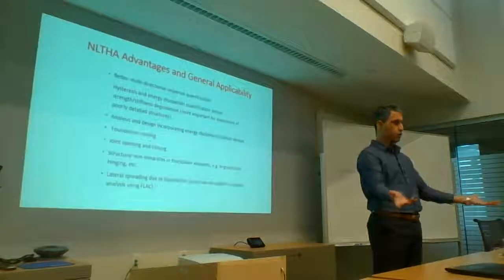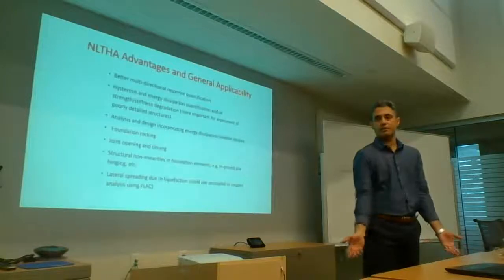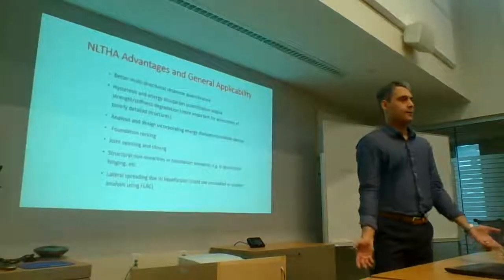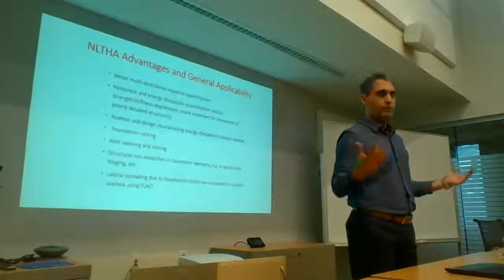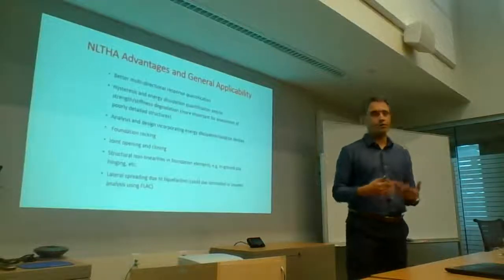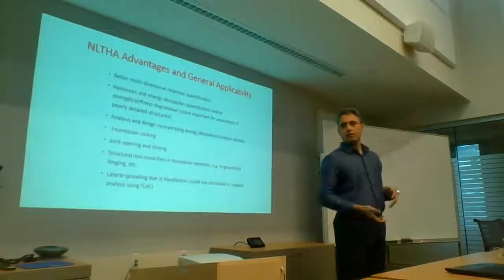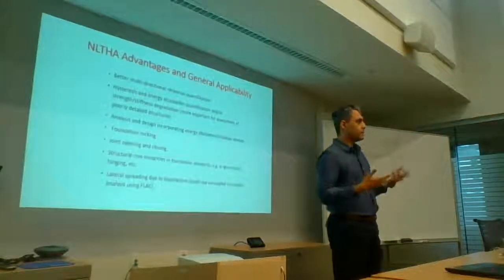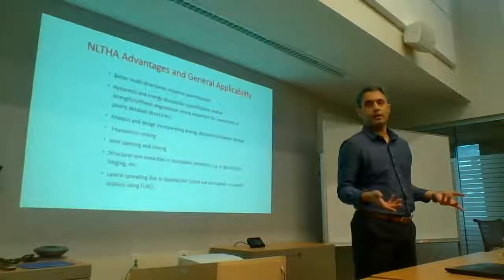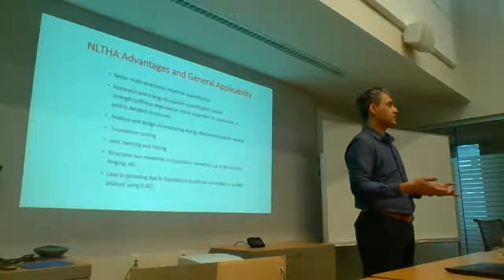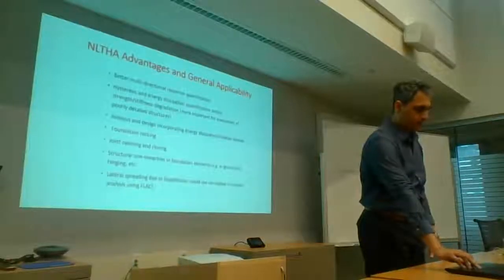Sometimes the deficiencies are so out in the open that you might not even do an analysis on the as-built structure. Okay? There are typical detailing deficiencies that people know about, and if you see lap splices in your plastic hinge zone, if you see your rebars are curtailed all over the place, if you see your shear reinforcement is 10 M's at 400 mm, there is no real reason to say, oh, I'm going to go run a shear model on it. I know 10 M's at 400 or 15 M's at 300 is just not going to work. So move on and do something more meaningful.